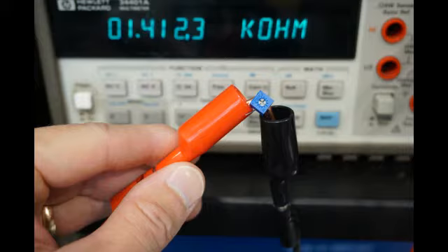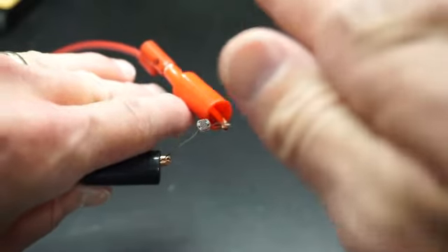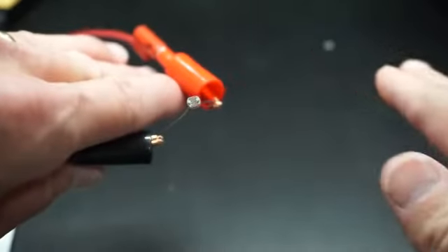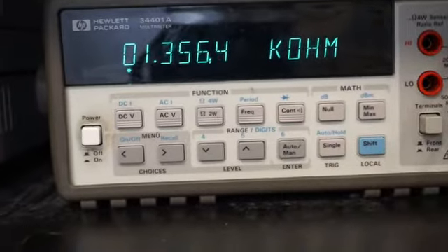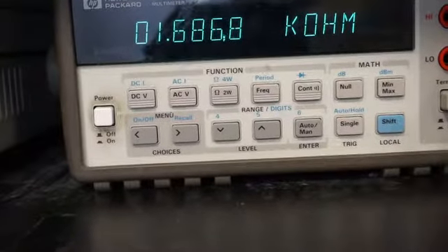When finished, measure the resistance of your potentiometer on the ohm meter. Compare your value to others. Although not in the procedures, you may also be interested to find out the resistance of your photoresistor when illuminated and when shaded.